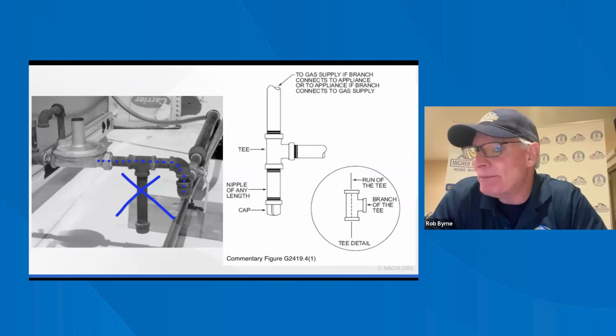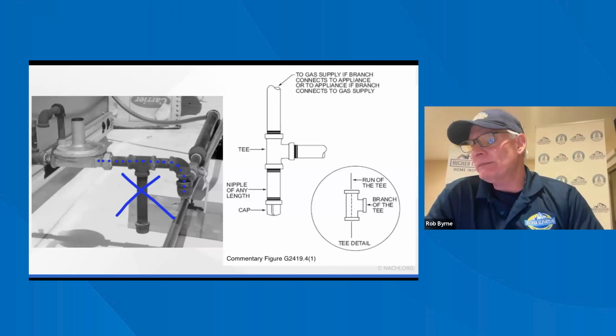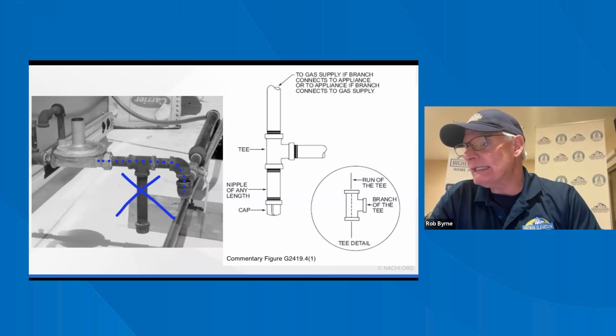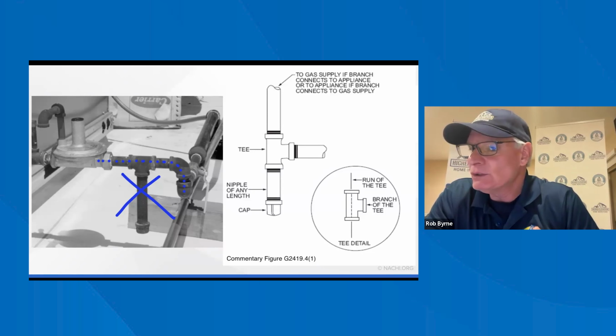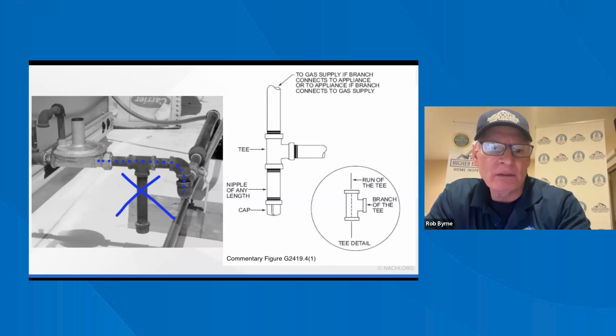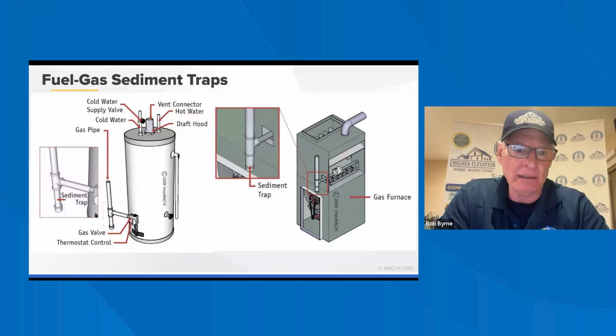Fuel sediment traps. We talked about that sediment trap design to turn the gas flow 90 degrees at the sediment collection point. So where is a sediment trap? So that's what they're talking about. You don't want it here. You want it on, like, this slide, right down here on the bottom, underneath that T that we talked about earlier.